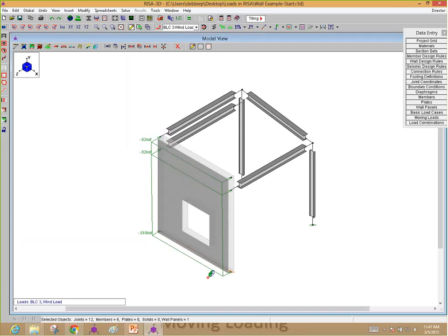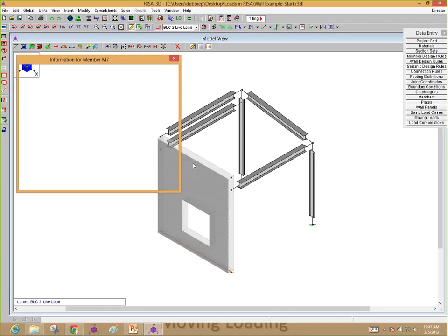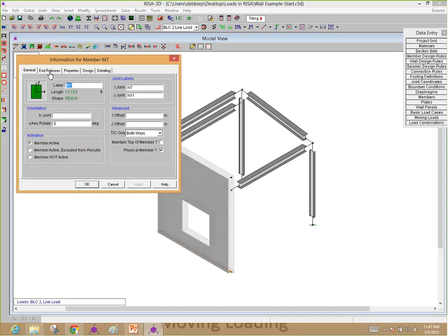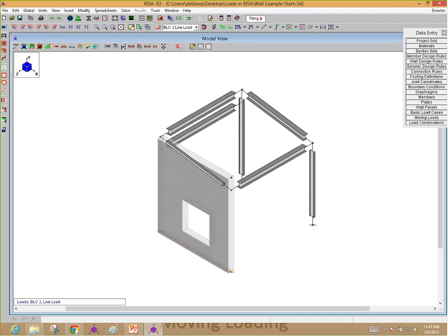So you've got wind loading. The next one maybe is some live load. Maybe we'll just do some area loads for the live load. So what I did do in this model, let's go ahead and just show that there. I put a little beam in here. It's just a false beam. If I want to use the area loads, I do need to have a beam along the edge, but once I do, it will connect to the wall just fine. So I just put a little dummy beam, a 4x4 to help me collect this area load, and I'm going to apply that to my structure.